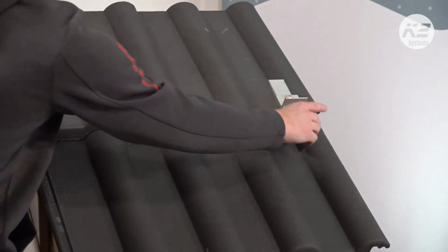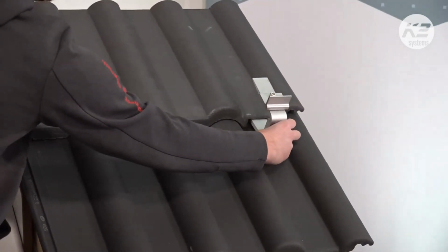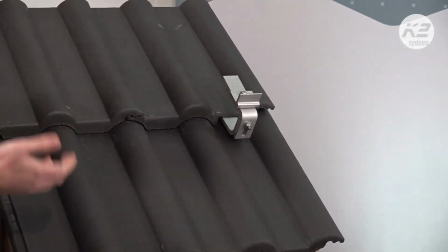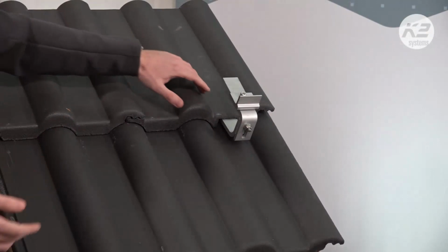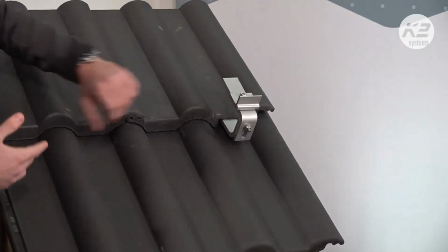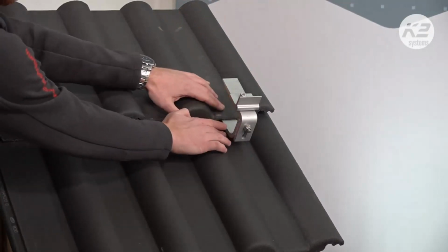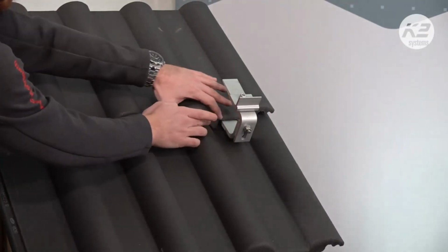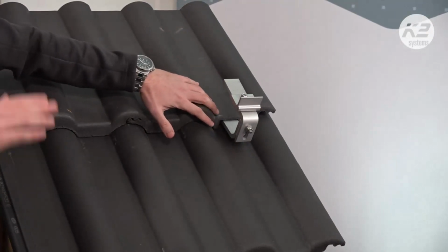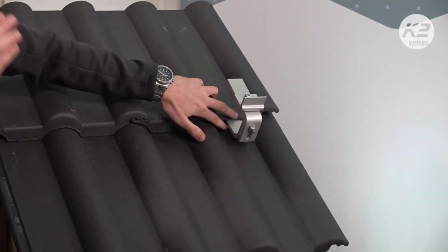So that's why we use the hooks from aluminum. And there are other tiles which are hard, and it's hard for me to cut them from both sides. That's why I will choose the steel roof hook, which is thinner, so it requires me to cut less of these tiles. So as I said, there is no concrete answer. It's about the situation of your tiles.